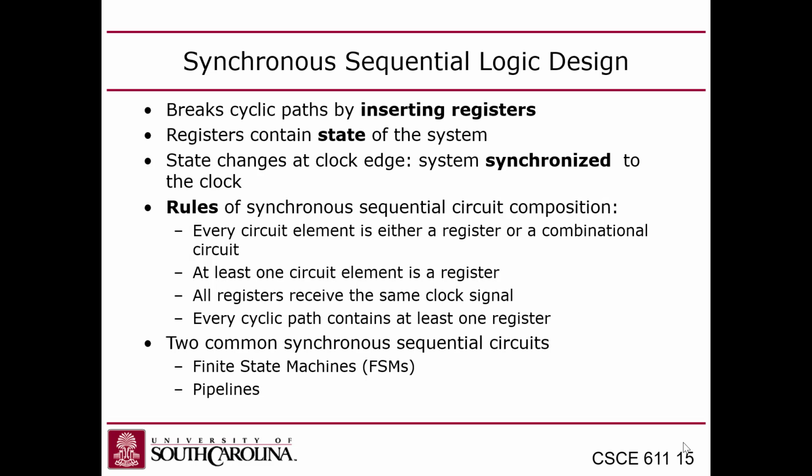So assuming that you can only do one stack operation per cycle, or one ALU operation per cycle, how many cycles is it going to take? It's going to take a cycle to pop, another cycle to pop, a cycle to calculate, and a cycle to push. So it's going to take 4 cycles.